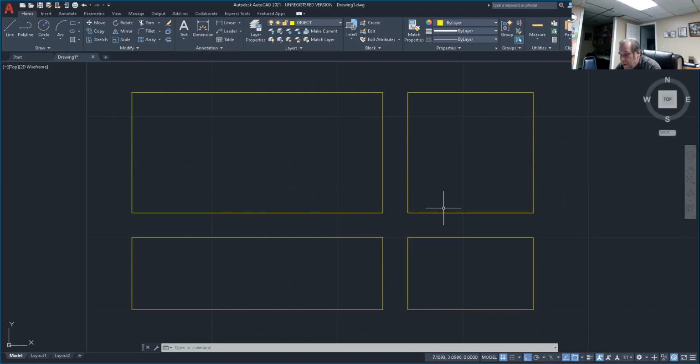Now dimensioning becomes very simple if you dimension by features. We need to draw this by features. So what I want you to do is first decide which feature you are going to draw first. You have to think about how a machinist would do it, and we'll talk a little bit about this later on. We'll go over how a machinist would approach building this part. So we're going to create that notch in the front view that just comes down like this right here. Do you see that notch?